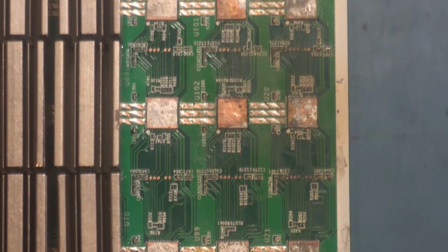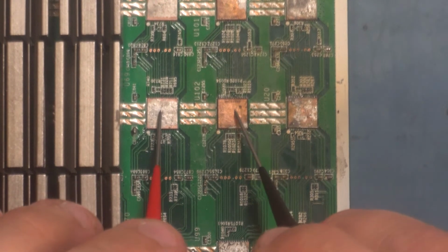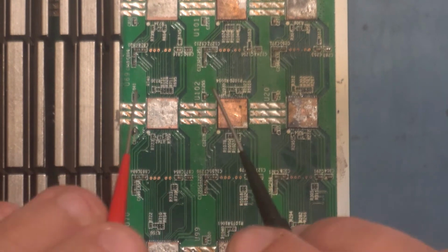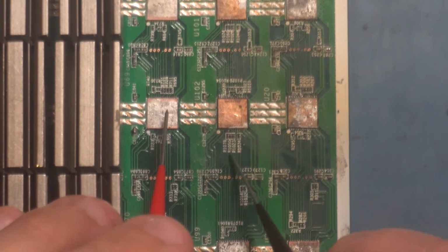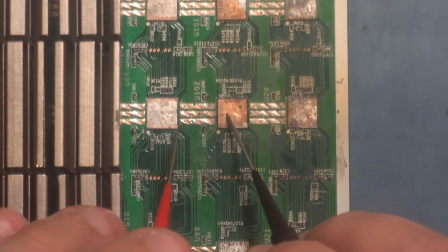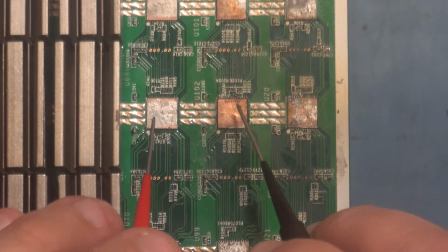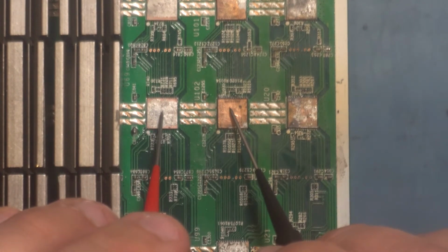And we know that when we measure the domain voltage, we measure from the top of the chips, right? Or the top of the heat sinks. Well, the top of the heat sinks are electrically connected to the top of the chips, and hopefully the top of the chips are connected through the chip to their respective grounds. And there's some subtleties there, but let's not get into that as part of this video. Let's just assume that they're directly connected to ground.